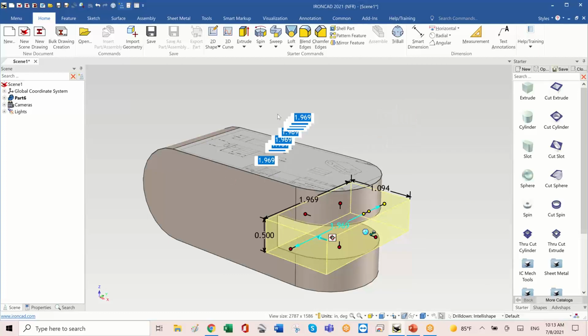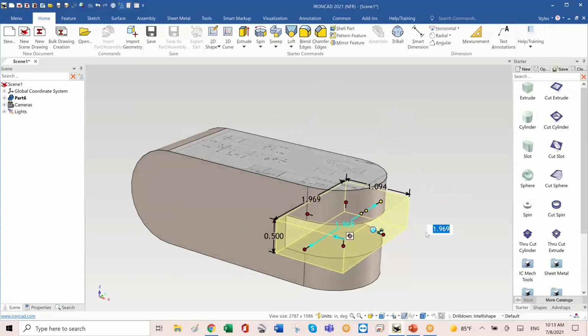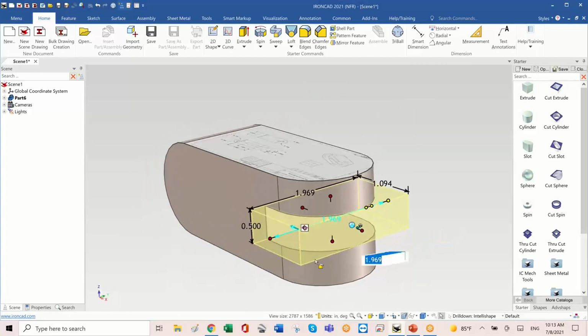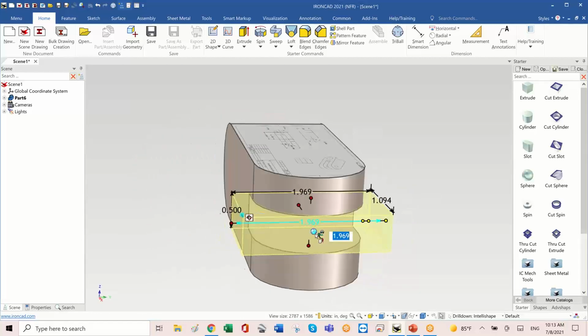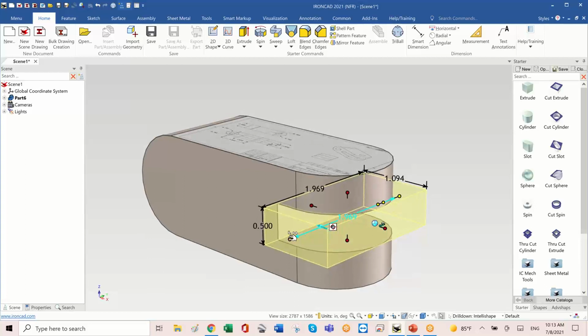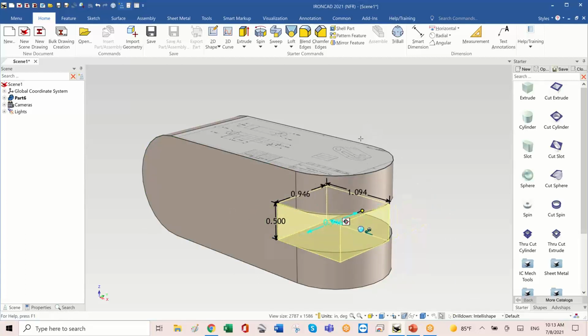No problem. Okay, so you'll notice that I put that 1/2 right into position, but now I don't want it to cut over the outside. I want it to match the side. So I can drag like this, but if I hold the shift key down, it finds geometry. So as I'm dragging, I'm saying, find this line.